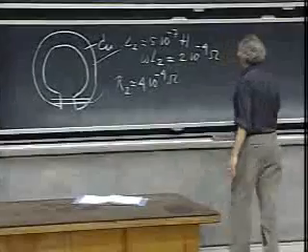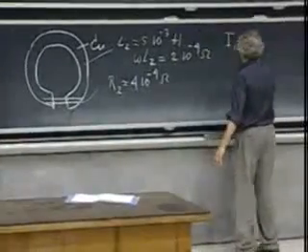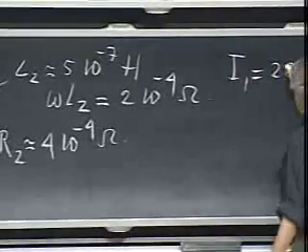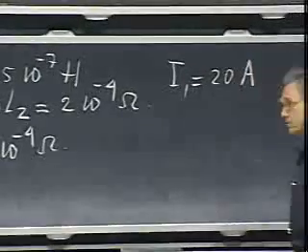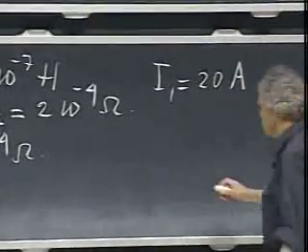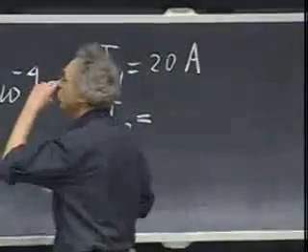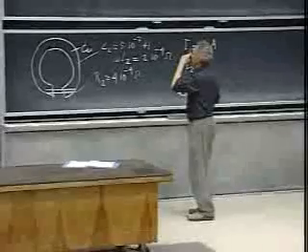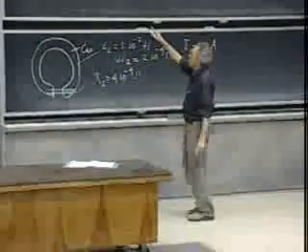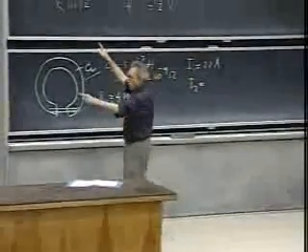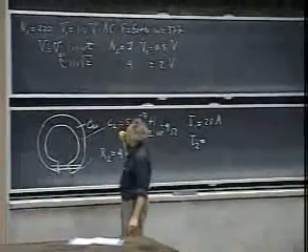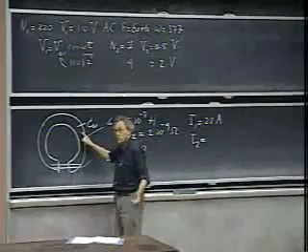I1, the current that I drive in the primary, is going to be 20 amperes. I do not expect that I2 will be 220 times larger than I1, because I use the same 220 windings for the coil, and this is just one winding.